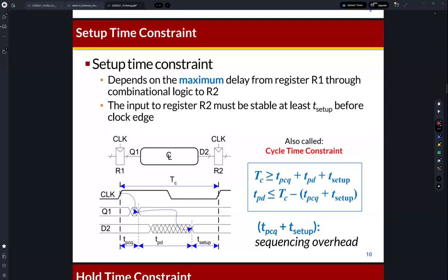It's a good question. He asked about the delay we learned for the simulation in the test bench, but you need to remember that the test bench is just simulation. It's fake. For the simulation, we just use the delay, but this delay is just to avoid some timing issue, like the exact timing of the rising edge. So we just add some delay after the rising edge for the input or output signals.